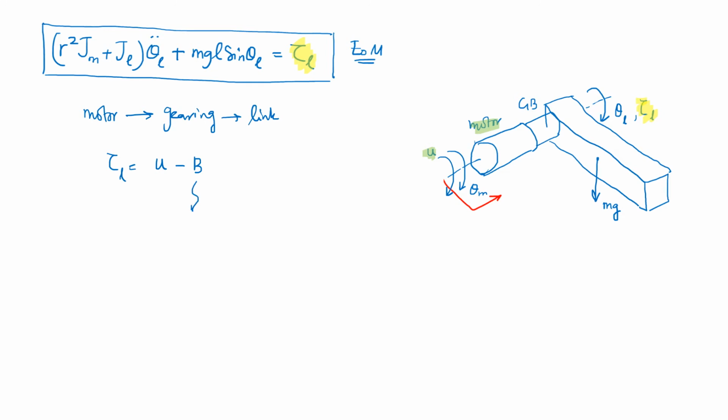So that is actually in true sense equal to R times the damping available at motor plus damping available up till the link. So this damping multiplied with theta L dot is going to be the component taken away from the motor torque. So that is the expression that we have to kind of plug in over here.